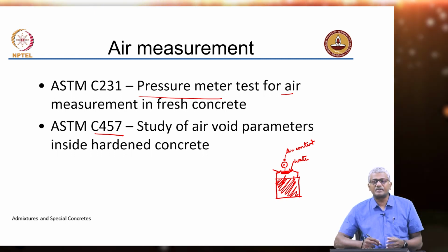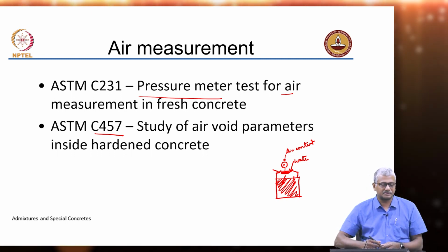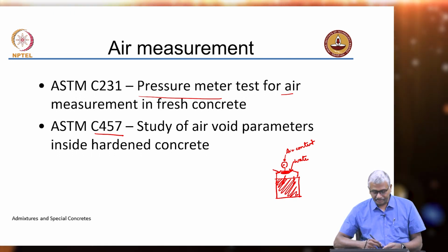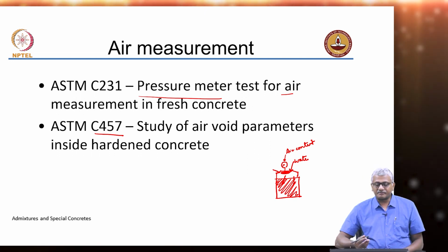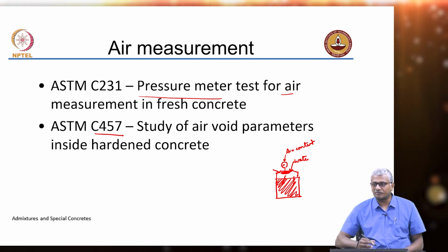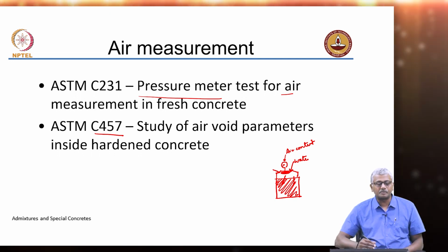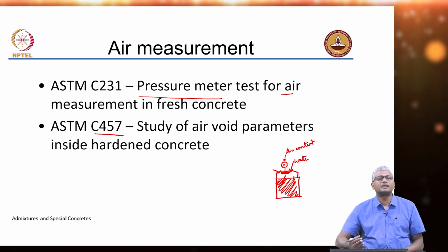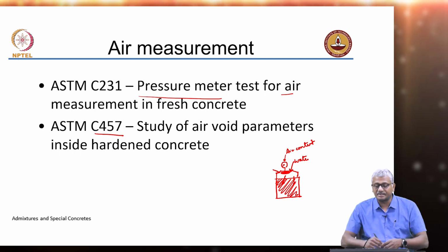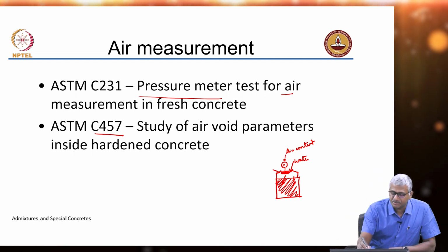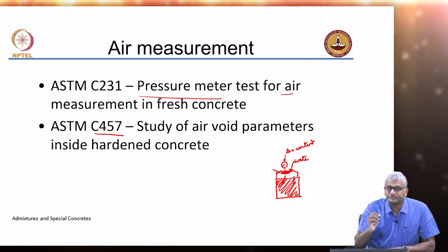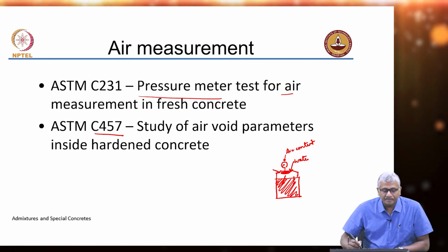So, there are several ways of classifying cements. I am just giving you some principal classifications based on ASTM, Indian standards and European standards. ASTM classifies regular cement, as per the ASTM specification C150, into 5 types. One is general purpose, which in India we call ordinary Portland cement. Type 2 is moderately sulfate resistant with moderate heat of hydration. Essentially, this means lower C3A and C3S. Then you have type 3, which is high early strength.